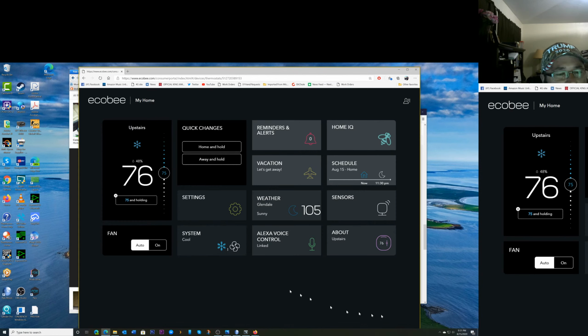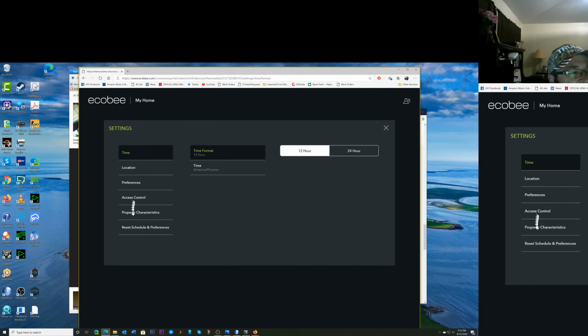So yeah, right here, it's down to 1 stage. We're at 9:30 at night, so it's 1 stage, and as it starts cooling off, here's the temperature right now, guys, 105 degrees. As soon as it starts cooling off a little bit, it'll go all the way down to 75 on the first stage. But right now, when it lets go, it just stalls and stays 1 degree above because that's how I have it set. You can go through and set all this stuff